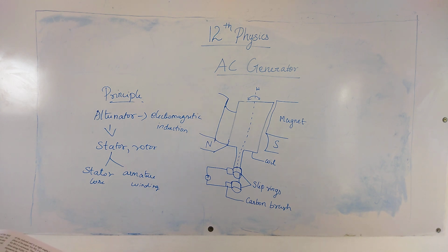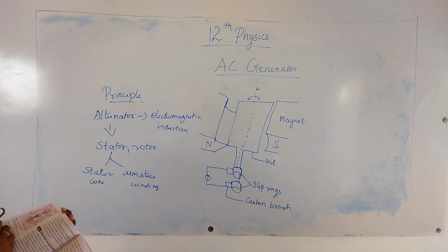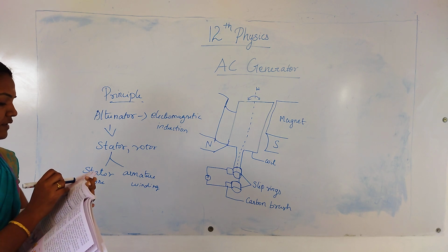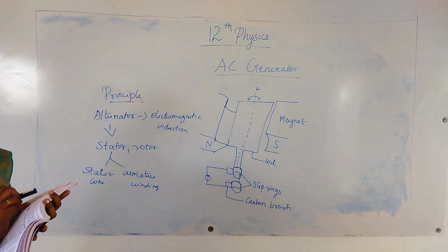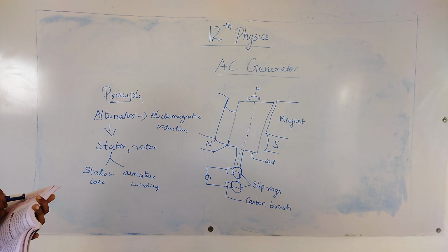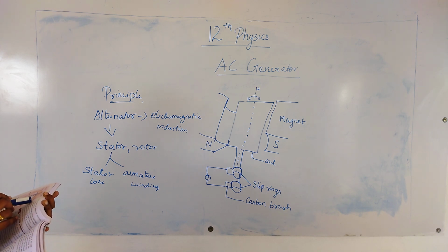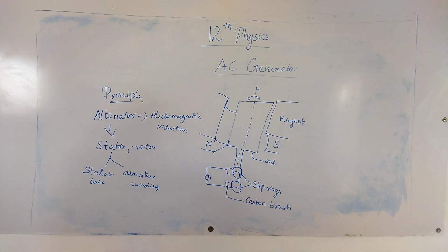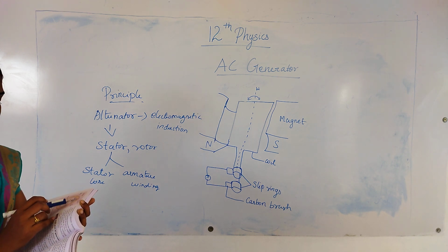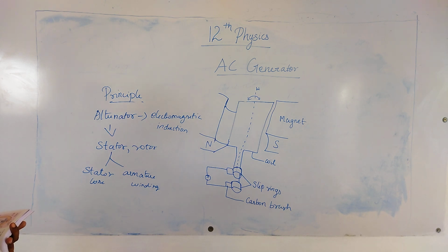See page number 224, figure 4.27: stator core, armature winding and 2-pole rotor. This is the diagram for the stator core, armature winding and 2-pole rotor. Here there is the armature slot at the top, then the round structure is called the stator core, and below, inside that, the slip rings are present. Then the magnetic axis of the field. Then there is a coil-like structure, that is called the field winding. Then the DC source, with two brushes on the slip rings. These are the structures of the stator core, armature winding and the 2-pole rotor.